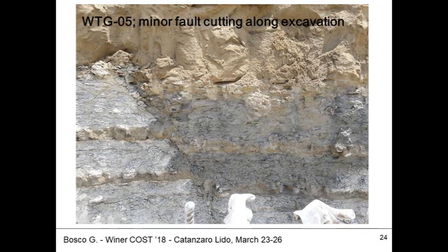One thing that is fantastic about looking at this large excavation is that you understand how narrow, how limited is the information we get from boreholes. Even if we have a large amount of boreholes, it is very unlikely that you could see a fault as we see over here. You see that this material has been dislodged with respect to the nearby material.